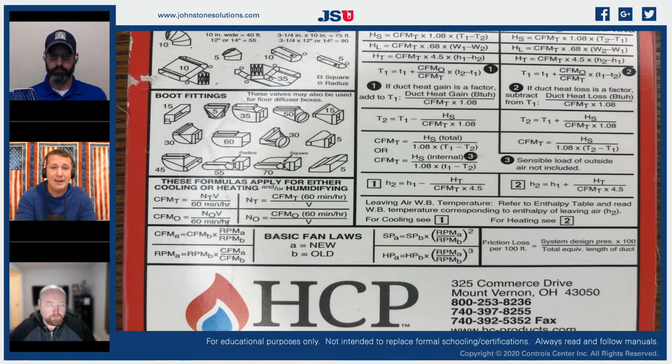So now what we have to do is actually add all of that together. If we're going to do this properly, we need to take all of our fittings and start adding those as part of our total duct system. This is where you get into your effective length. This is where you start looking at your entire duct system to see what size you actually need to use.